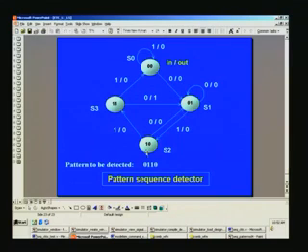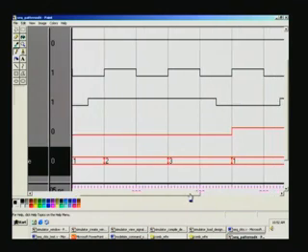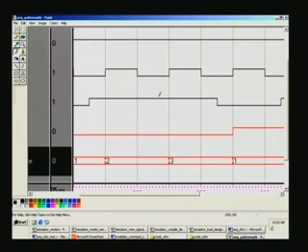So, we are taking the path once again here. So, S1 to S2 should go provided input is 1, right, S1 to S2 it has gone provided input is 1, right, and here again 1 1 here, right, again you see, notice this pattern 0 here, then once again 1, then one more 1, again 0, isn't it. So, the output is also correspondingly 1. So, you can see 2 to 3 transition here.